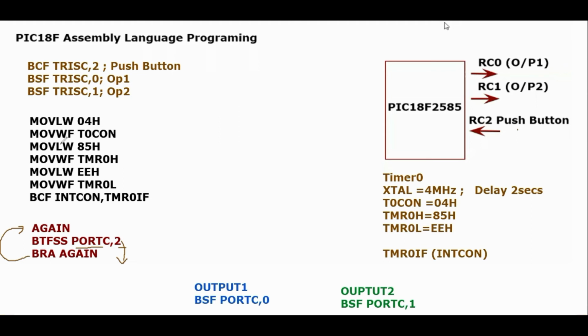First of all, you will start a timer and continuously check whether this pin is still 1 or not. And if the timer expires for 2 seconds, that means the pin was consecutively 1 for 2 seconds. That means we need to switch to output 1.